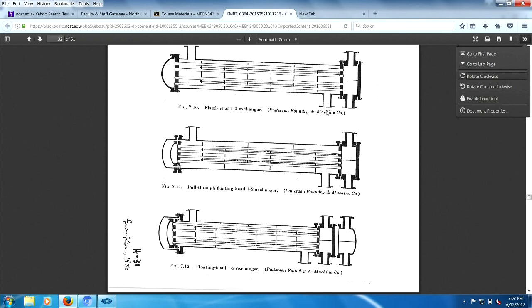They're put in there to direct the flow. There are two flows here: the pipe flow, or tube side, and the shell side. Shell side flow, perhaps the stuff comes in here, comes down. You want it to go across the tube bundle. This will be a bundle of tubes.